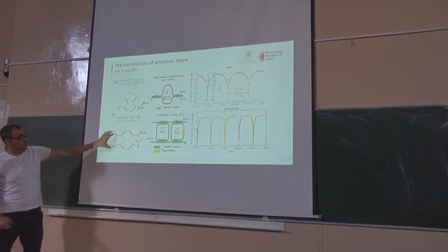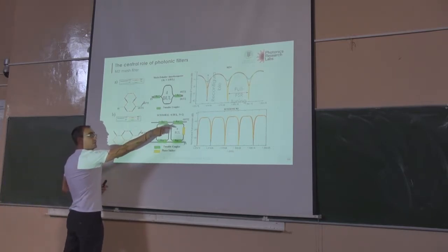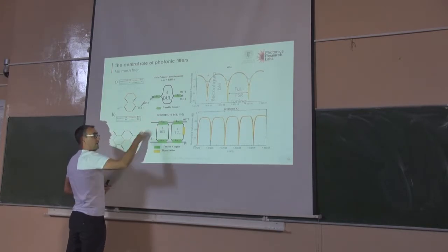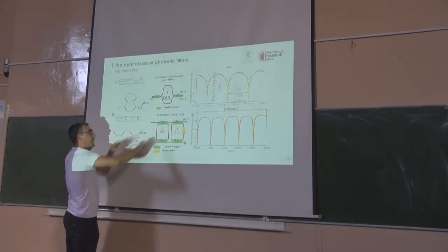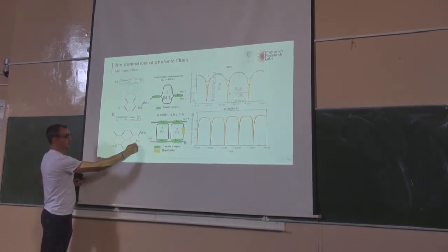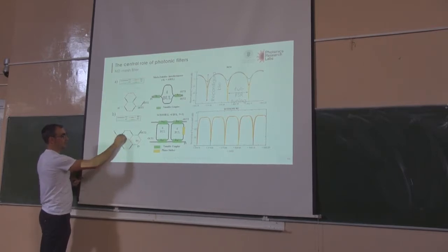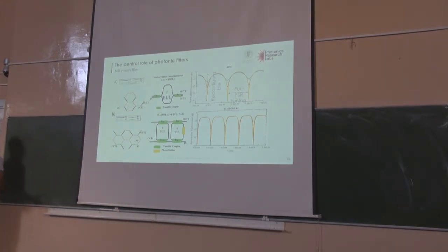And then it is not easy to see, but you can also make a scissor filter, which consists of two rings coupled to one and two waveguides. They are not coupled in between them, they are apart. Okay, and this can be done with this configuration: in and then this way out. This is one ring, and this is the other ring. Okay, and this is the second one. So it's a totally reconfigurable architecture.